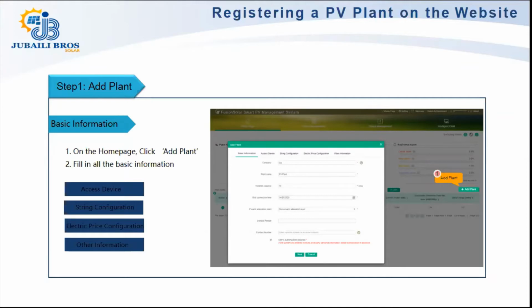So you must put the right serial number, and this is a very good way of checking that you are putting the right serial number onto the FusionSolar, so that it looks into the FusionSolar management and sees if a device of that serial number is connected to the management. That is a step we already discussed in the local commissioning, like how you create, commission and connect it to the FusionSolar.